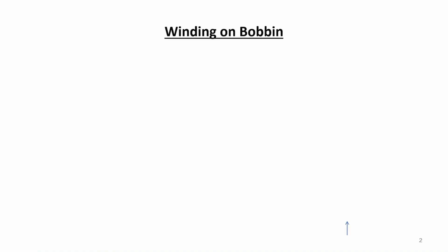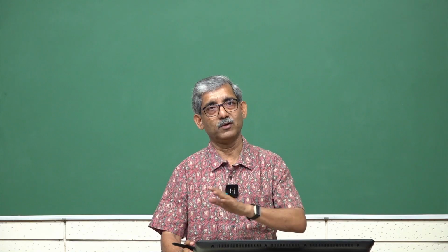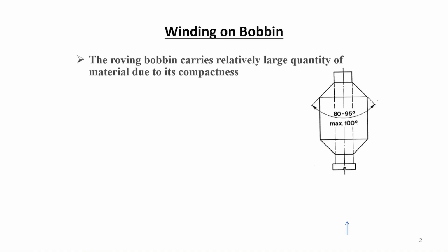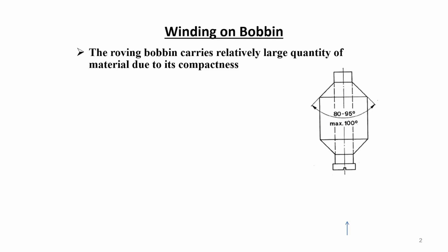So, winding on a bobbin is very complex, where the bobbin gets driven from the epicyclic gear. Here again, we will discuss that subsequently. So, here if you see, the twisting is not that critical, because twisting is done by the flare which rotates at constant speed, but winding is a complex system.